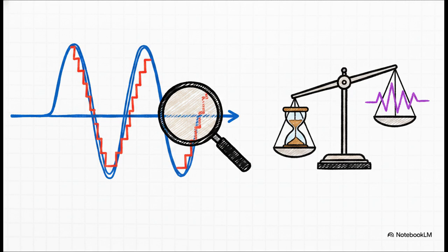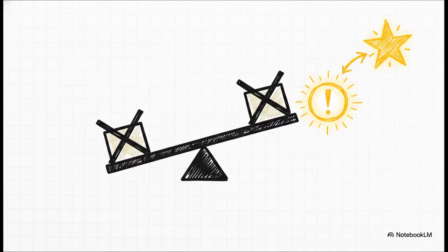Now listen closely, because here is the classic trick. The exam is probably going to give you the sampling frequency, f sub s, not the sampling time, t sub s. You have to consciously remember that t sub s is equal to 1 over f sub s and swap that into the equation.